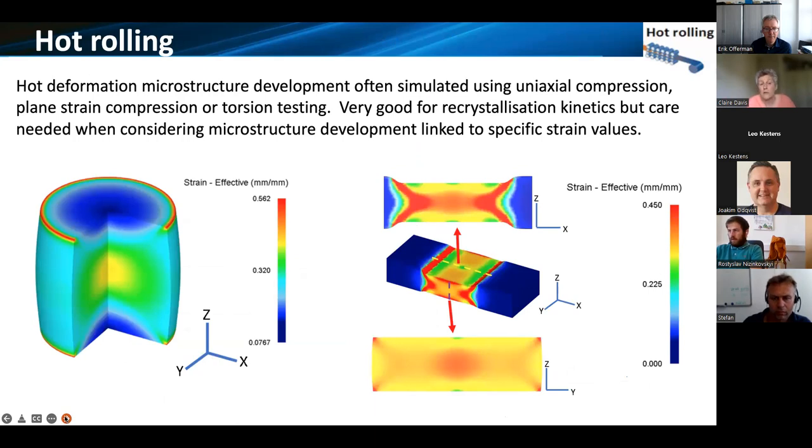Whilst talking about hot rolling, I also ought to mention the importance of our experimental simulation of behavior and understanding that, particularly when looking at microstructures, and that's where our focus is today. So for lab behaviors, we can have lab hot rolling. One of the challenges is maintaining the temperature as we go to smaller samples when we do our laboratory hot rolling. And particularly if we're looking for control of the strain and temperatures and interpass times, it can be challenging in a lab mill.